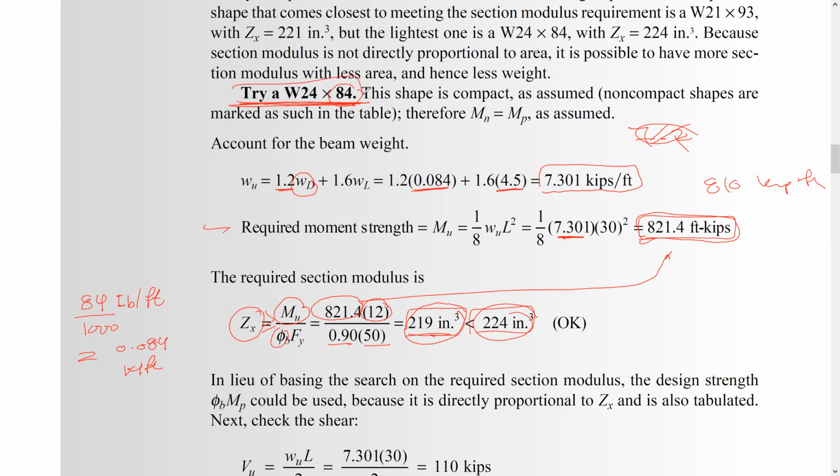So let's use table 3.2 for wide flange here, if we deal with wide flange, and see how much phi b Mn this is for the LRFD method. So how much this value, and this value here, which we'll get here, is supposed to be greater than this value. It should be equal to or greater than this value. So let's go to table 3.2 and see how much this value is.